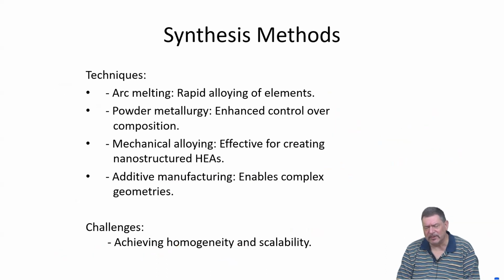Now, how to make these materials? You know, there is a range of methods which probably you use yourself. And actually, they are also used for high entropy materials. There's a lot of melting synthesis pathways going on, and they use conventional arc melting and things like that. Obviously, when you come from the liquid phase and you have nucleation and then rapid crystal growth, there is always the chance to have other phases forming maybe in the interdendritic regions or so.